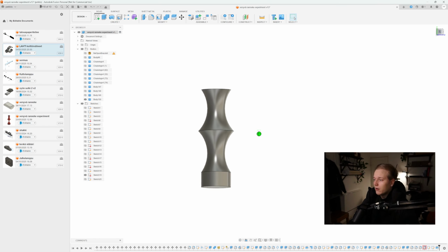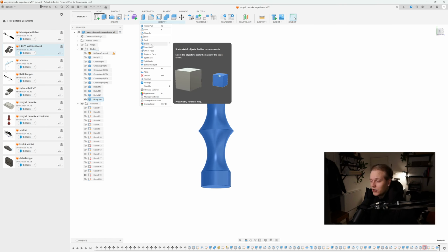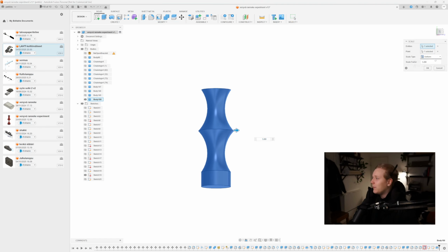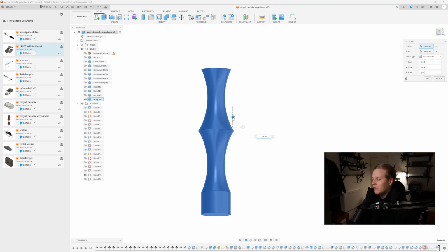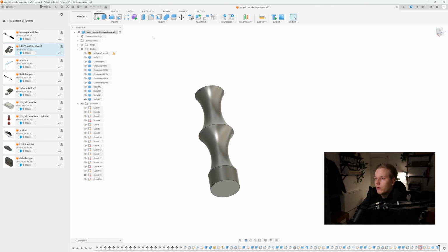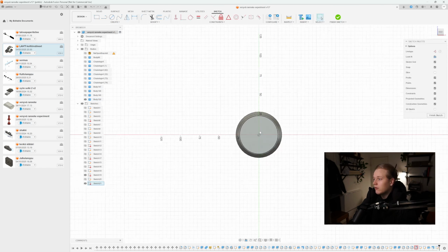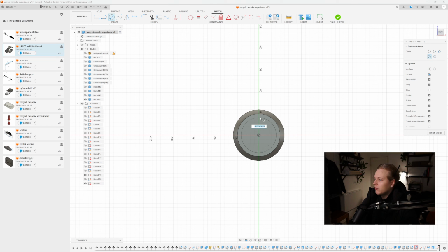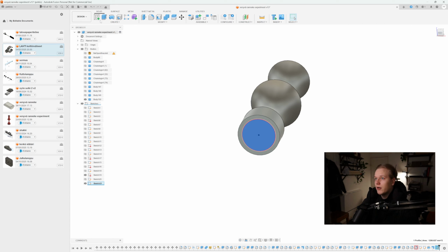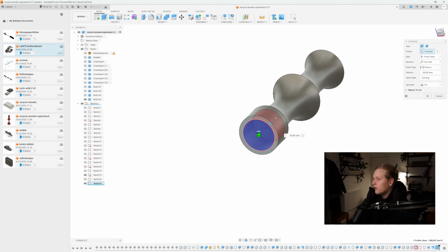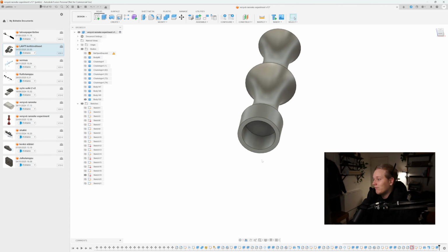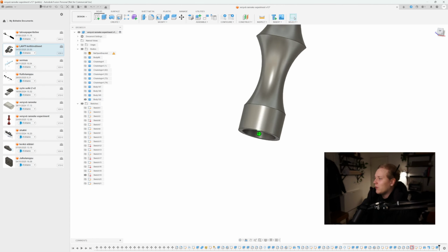So now we're pretty far already. I don't exactly love the shape, so I'm gonna scale it a bit upside like this, so it's taller. The shape is getting better. Now I'm gonna start doing some of the finer details. I'm gonna create a new sketch on the bottom here, and we're just gonna create a circle like so, really simple. And we can drag that back with the extrude, so you can cut with extrude as well, which can make it easier to make complicated objects like this.